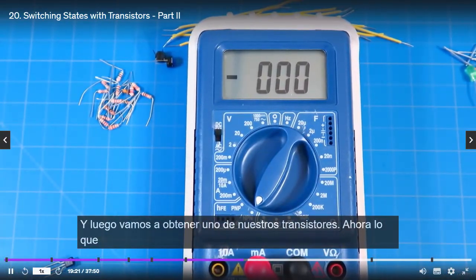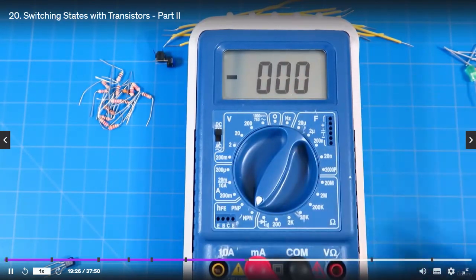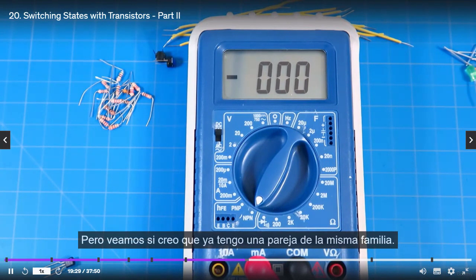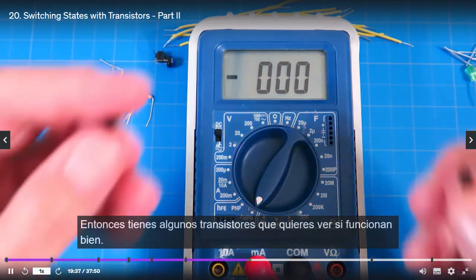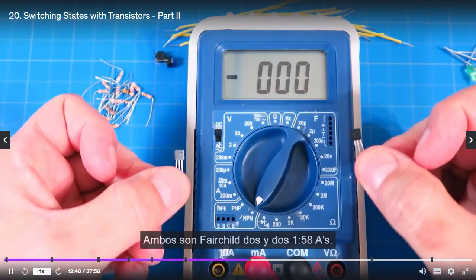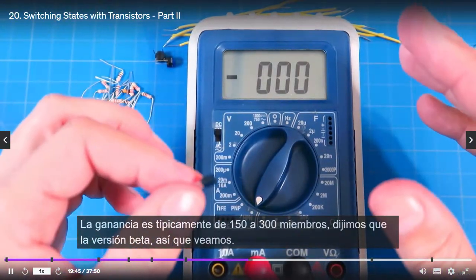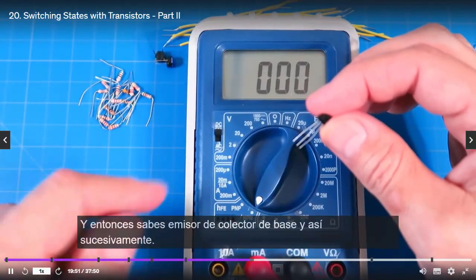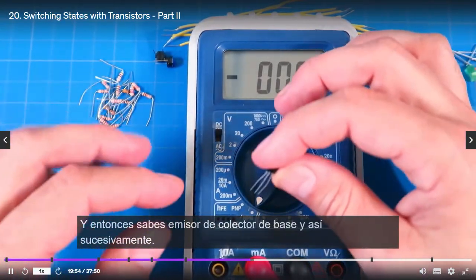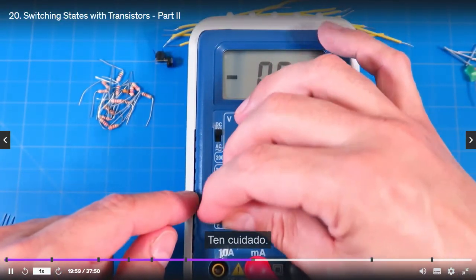Then we're going to get one of our transistors. What I want to do is get two transistors from the exact same family. I think I've already got a couple here that are from the exact same family. There's one, and there's one. So you've got some transistors and you want to see if they work. These are both Fairchild 2N2222As. The gain is typically 150 to 300. So we're going to put it in, and you see it says emitter, base, collector, and then base, collector, emitter, and so forth. We're just going to put it in assuming this is emitter, base, and collector, which I think it is. Be careful.